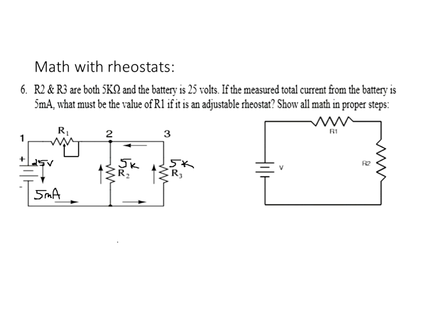Probably one of the harder problems to solve, although it should be quite easy for you. What you need to find here is, I know the current and I know the voltage. The first thing I need to find is the total resistance. Let's do that. Well, the total resistance, RT, using Ohm's law, is equal to the volts total divided by the current total. Okay, the current total is 5 milliamps.